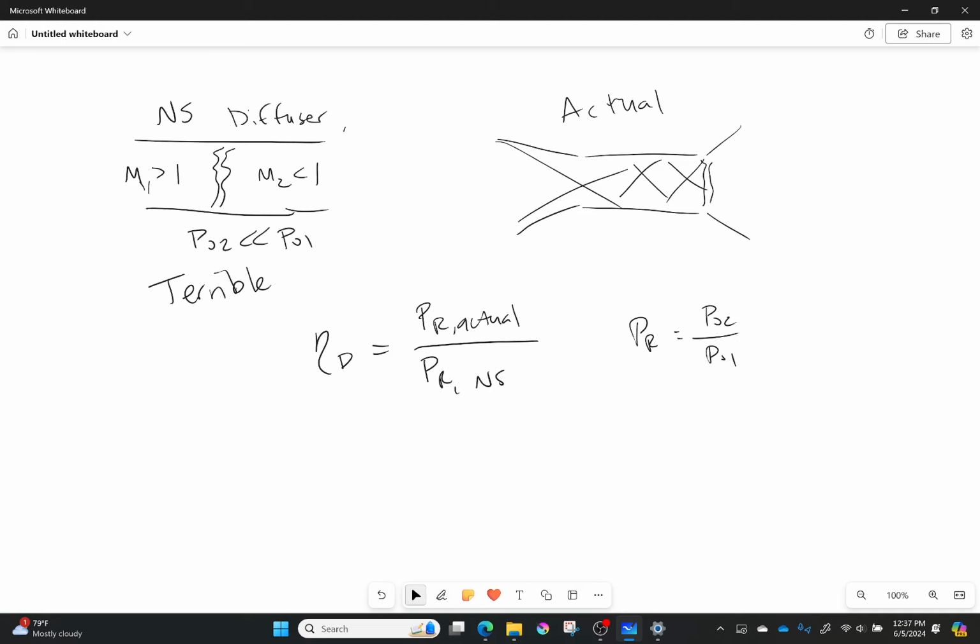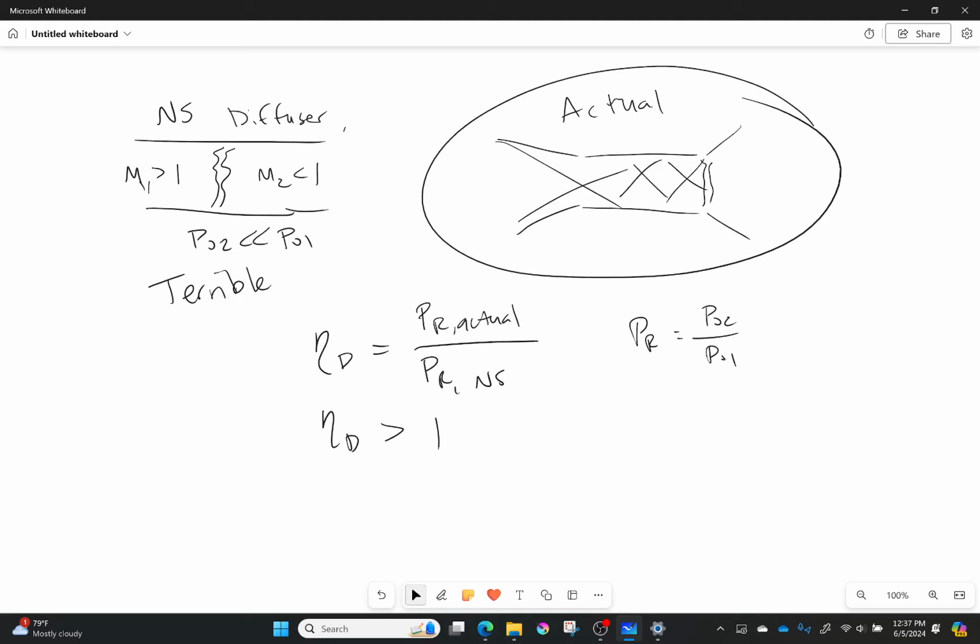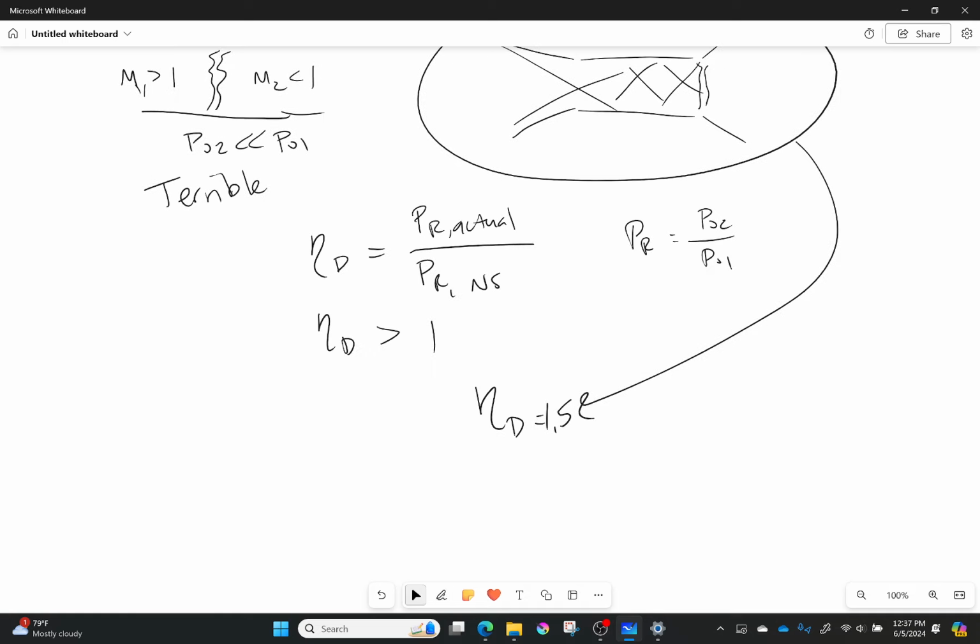So if I do a good job, if I don't do an absolutely horrible job, this should be more than 1. Because otherwise, why am I not just using a normal shock? Like literally, if it's less than 1, you've failed at your job. Okay, now let's come back to this scenario up here. So I've got this actual one, and I know that it has a diffuser efficiency that's equal to 1.5. Okay, so that's great. That tells me something.